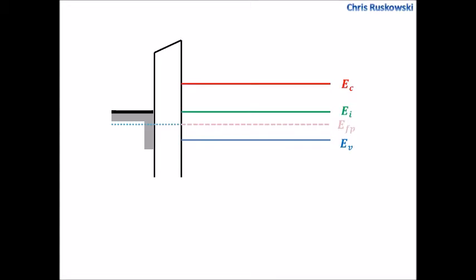Moving on, because of the metal work function, we actually do have charges inside of the oxide layer as well as charges induced into the metal and the semiconductor. As such, when we put the three devices together, there will be band bending. To counteract the band bending, we have the flat band voltage, the amount of voltage needed to make all of the bands flat. Here, with the calculation, it's basically the charge density internal to the oxide divided by the capacitance, minus the work function, calculated as such.